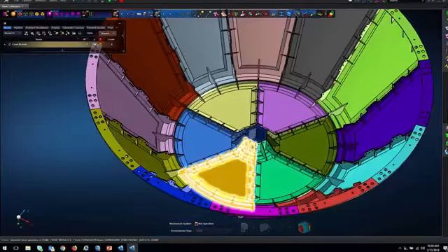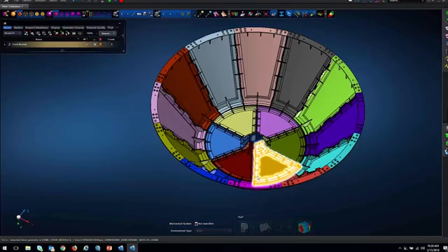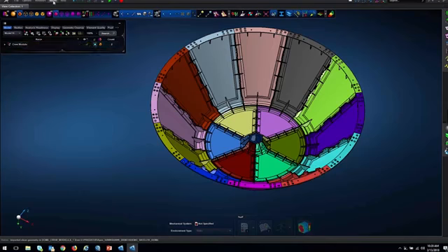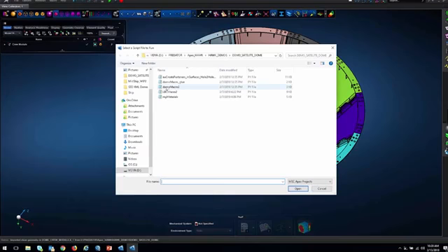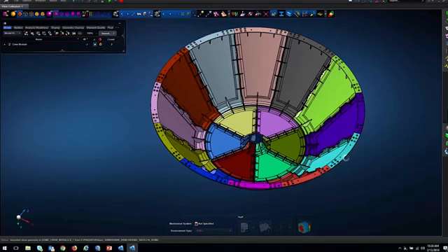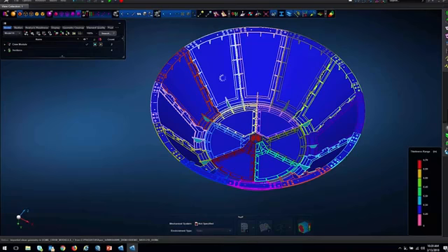Let's run a few scripts here and take a look at the power of the scripting, how it helped to create the meshed model, assembled model, and ready to run the simulation. Let's take a look at the first macro. The first macro in this case is created using the macro record. For one of the typical panels here, we run the macro to create the mid-surface, to assign the thickness, to extend all those parts, and create a congruent geometry, and mesh that.